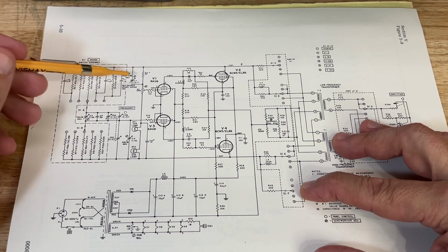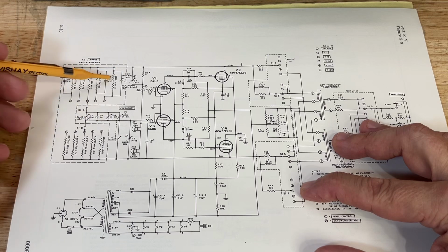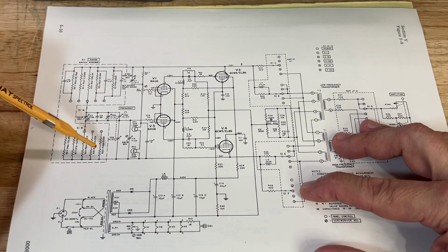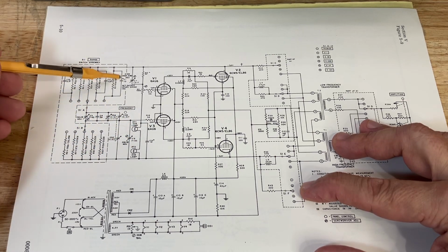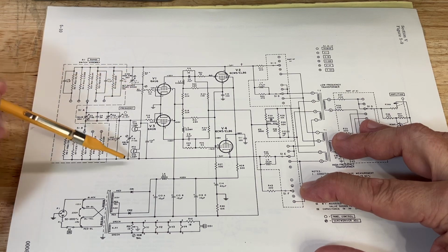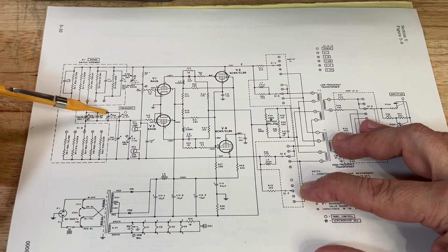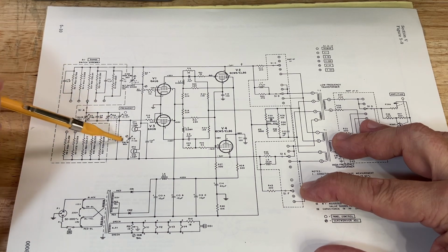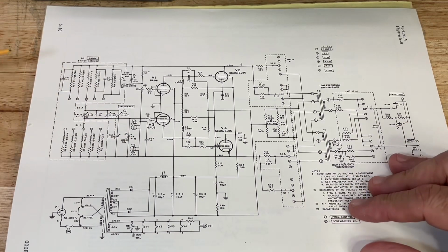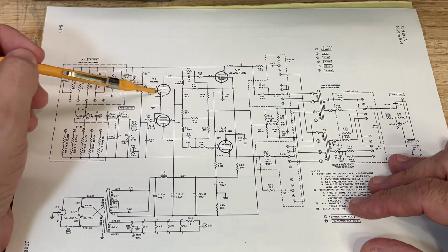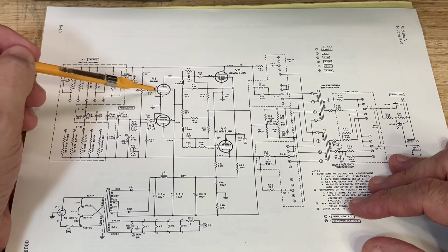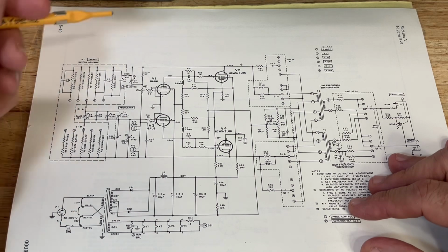So the combination of 1/2 R times 2C is the same as the combination of R times C. So this is essentially the same, except that it actually uses three capacitor gangs. Two of these are in parallel with one another, so they add their capacitance. And this one is just a single third gang of the tuning capacitor. So that provides your positive feedback, and the negative feedback is provided to the grid of this amplifier tube,